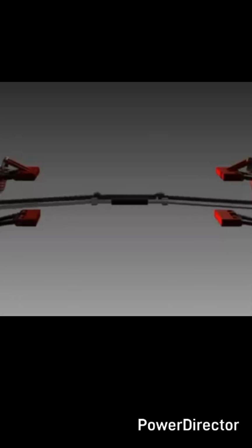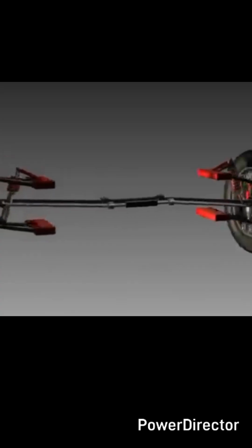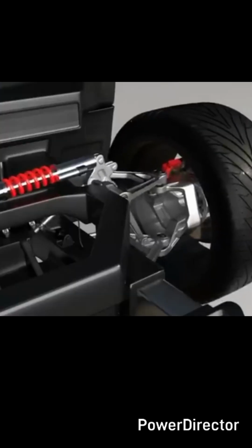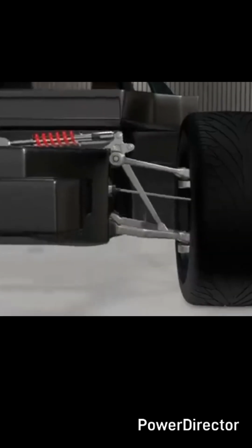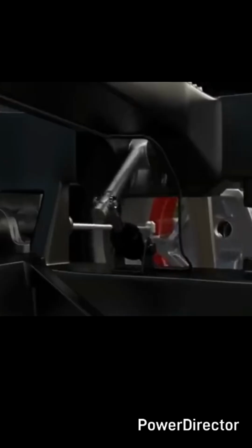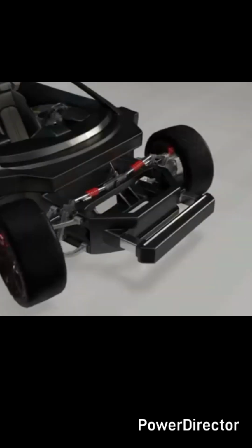When the vehicle moves on uneven surfaces, the wheel faces shocks. These shocks are transferred to the shock absorber through the lower link. The shock absorber absorbs the maximum amount of shocks. The upper link is used to maintain the camber of the wheel. This system is complex as well as costly, and it requires more space.